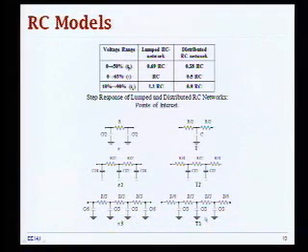Just to give you a flavor of the complexity involved, I did recently an example of a 16-bit multiplier with a latency of 4 pipeline stages, and a simulation of the entire multiplier, which has a fair amount of gates, without any parasitics takes about half an hour.